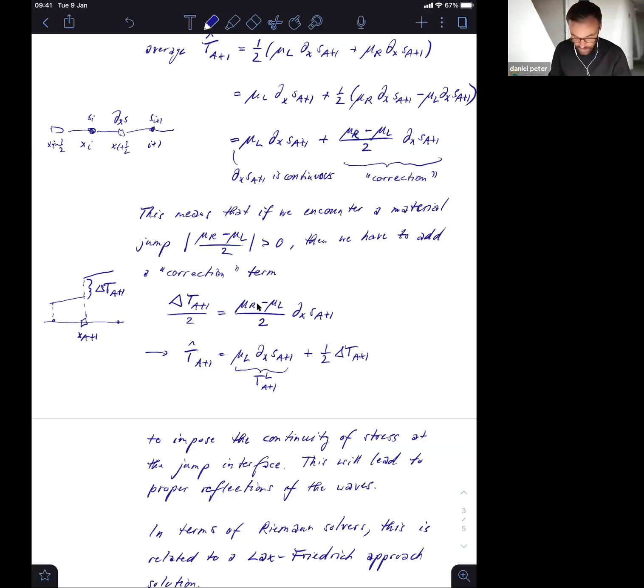And then obviously you would define here what the shear moduli would be, for example. You would have a shear moduli at i plus 1/2, here at i minus 1/2, etc. But you only have one value for that grid node, for that point. So which value would you take if you would have a jump at that position?